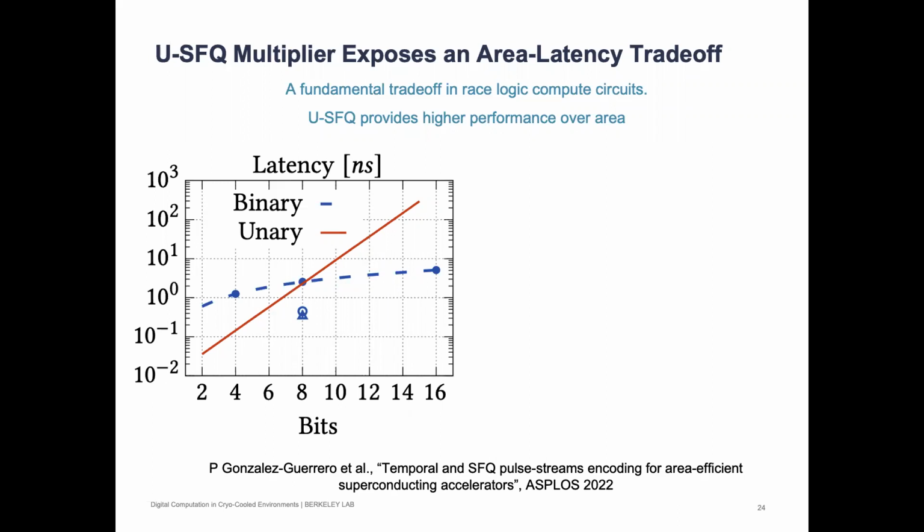So it takes twice as long to have an epoch, and each epoch produces 1 output. So that makes sense. The binary multiplier does get a little slower because the critical path gets longer and so on, but it's far from exponential. It's also sublinear, I think. So you can see that this multiplier really prefers to operate at lower bits. And for many applications, that's just fine.